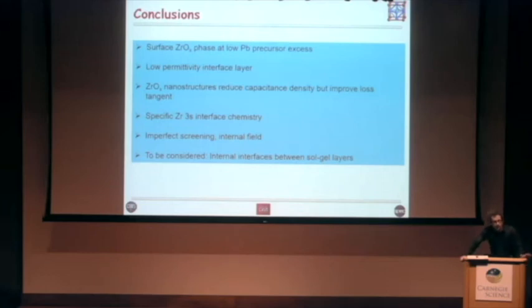We've seen this, it's reproducible first of all, so it's a real result. But it may be to do with the exact temperatures we've used for the crystallization. We do 2 rapid thermal annealings, one after the first layer, which is the seed layer of the PZT, and one after that. And as you know, because of the crystallization temperatures, there's a strong gradient between the titanium and the zirconium in each layer.